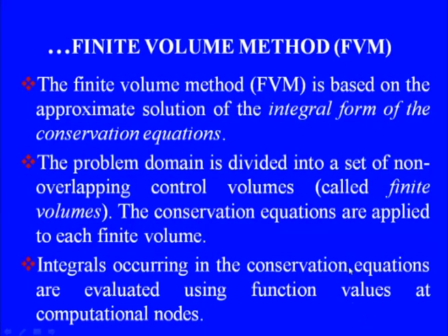And these integrals which occur in application of the conservation equation to each of the finite volumes are evaluated in terms of the function values at what we call computational nodes.